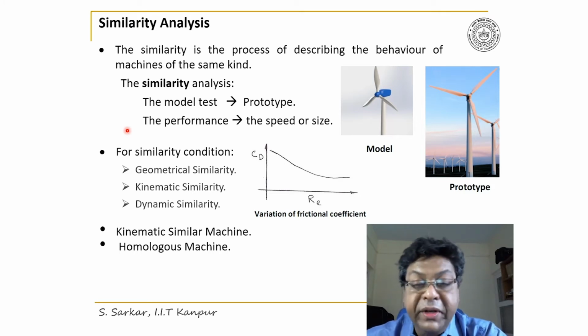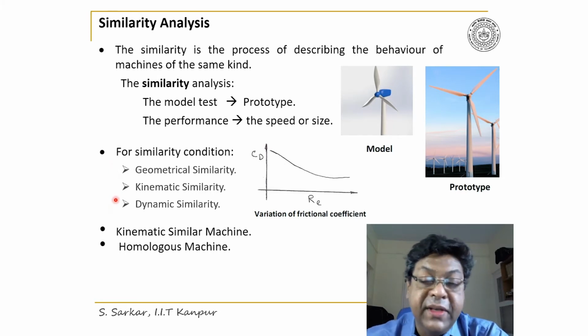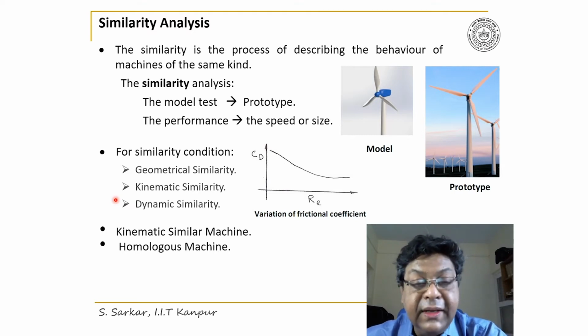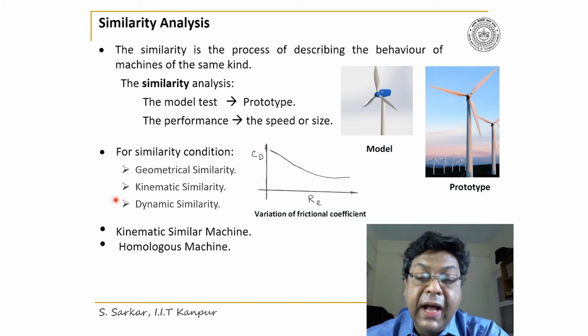This also can be done through similarity analysis. For similarity analysis, the following three conditions must be satisfied: first, geometric similarity; second, kinematic similarity; and third, dynamic similarity.